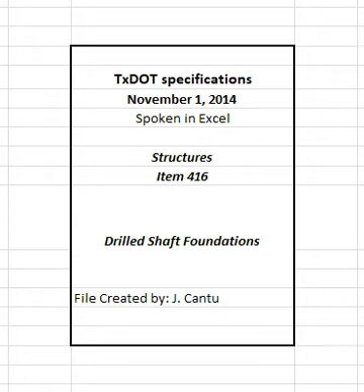Table 3. Mineral slurry requirements. See table in specifications. Use mineral slurry consisting of processed bentonite or attapulgite clays mixed with clean fresh water. Do not use partially hydrolyzed polyacrylamide, PHPA, polymeric slurry or any blended mineral polymer slurry. If approved, water may be used as the drilling fluid.